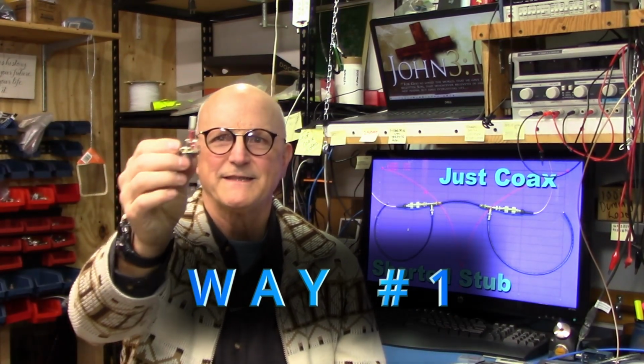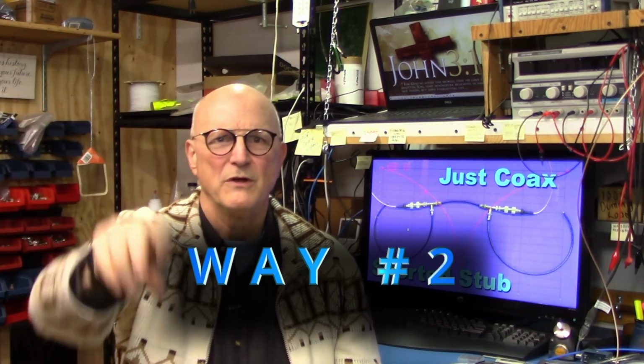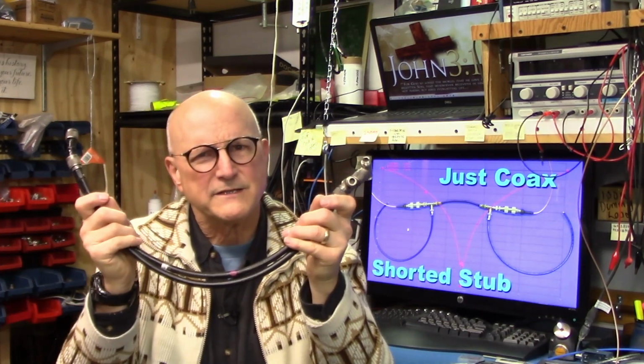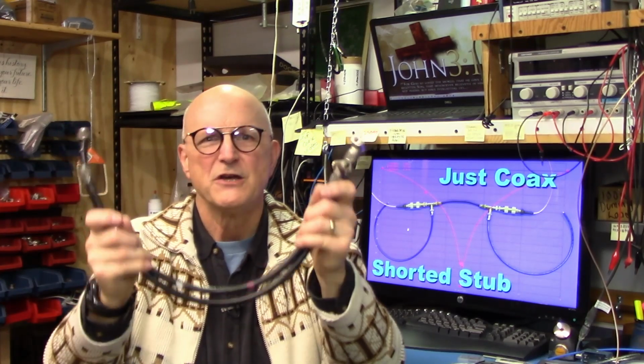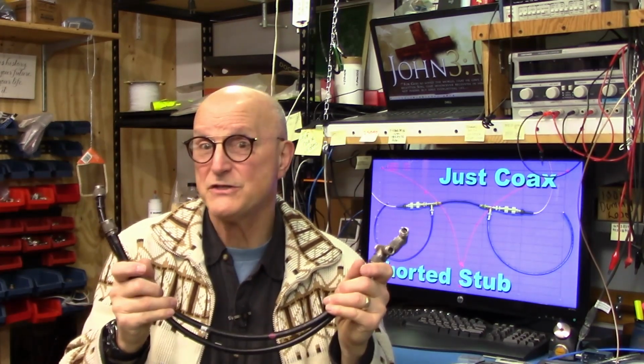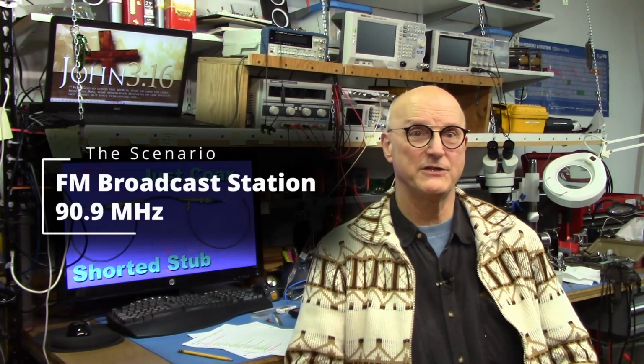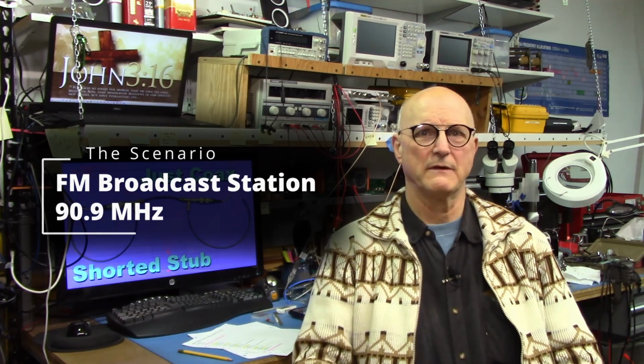All right, way one. You have a variable inductor like this little guy, and you want to know how long your coaxial stubs need to be to use your inductor. Way two, you already have prepared cables of a particular length, and you want to find out what inductance you need to make them work for your filter. So let's actually design a solution for these two scenarios using a shorted stub design. So here's the scenario. You live 5 blocks away from an FM broadcast station which transmits on 90.9 megahertz. And it is causing you some real issues. And you want to filter this frequency out.